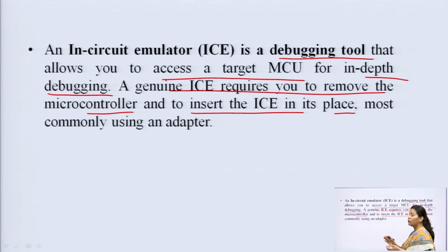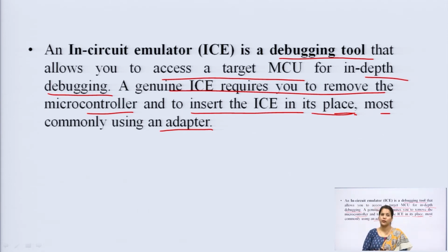Basically, we remove the main microcontroller and replace it with our ICE device. The ICE device is placed at that position, most commonly using an adapter. Using that adapter, the main microcontroller is replaced by the ICE, and we can test the actual working of the code on the target hardware. In this way it is helpful in judging the actual working of the code in our application.